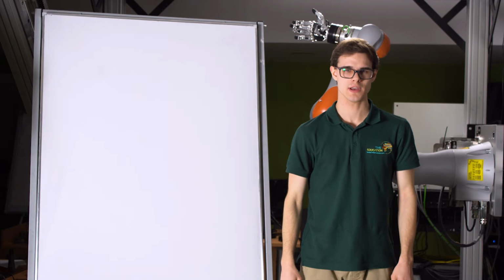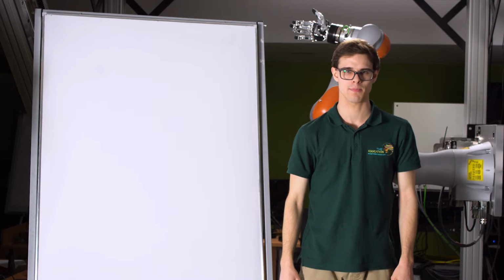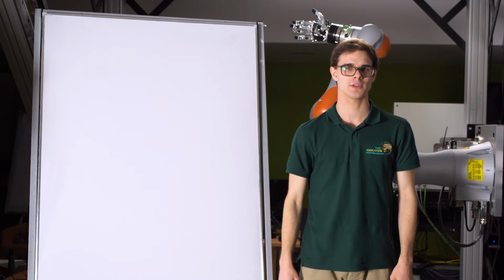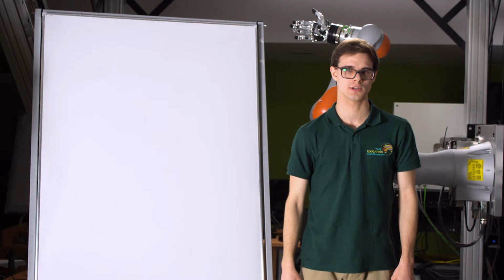In such a situation, you must ensure that both transistors do not turn on at the same time, because you will cause short-circuit current to flow through them. Transistors can be unipolar or bipolar, the same type of conductivity or different. The decision which one to use will determine the control system with protection against short circuit.